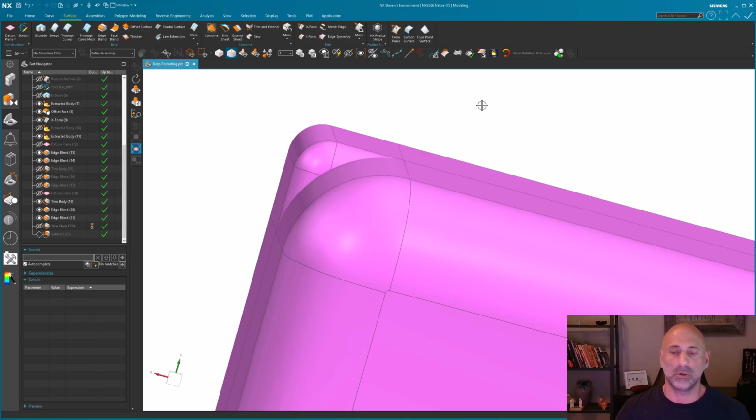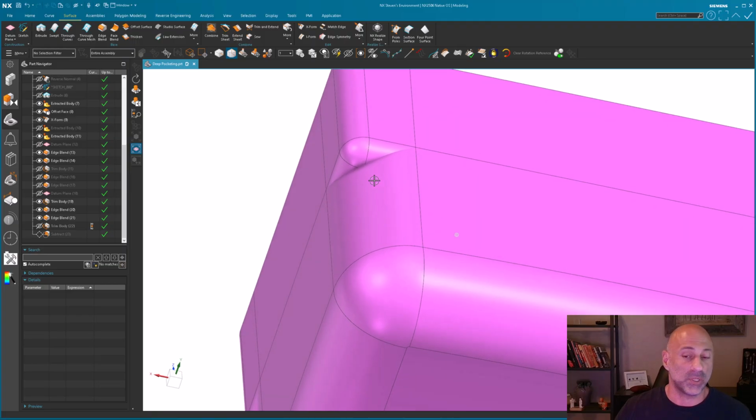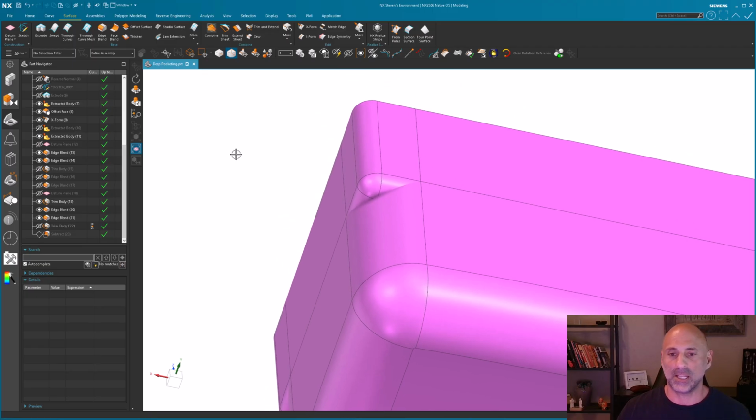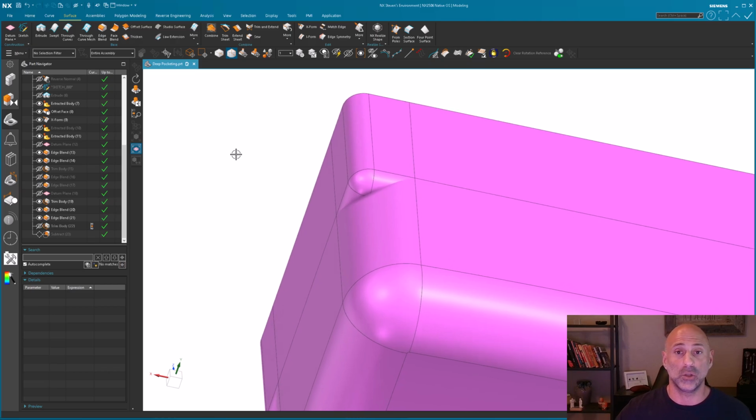Okay, so that is another thing that needs to be considered when you are doing your deep pocketing. Now, this is just good practice in general for any machine part, right? It's just good practice to have that because it's going to make the machinist's life a lot easier. And again, I know it's potentially adding a little bit of material in that corner, but it's better to have a slight bit more material and a part that's not going to fail, because some of those things that could cause a part to fail may not be caught with quality or inspection or anything else.